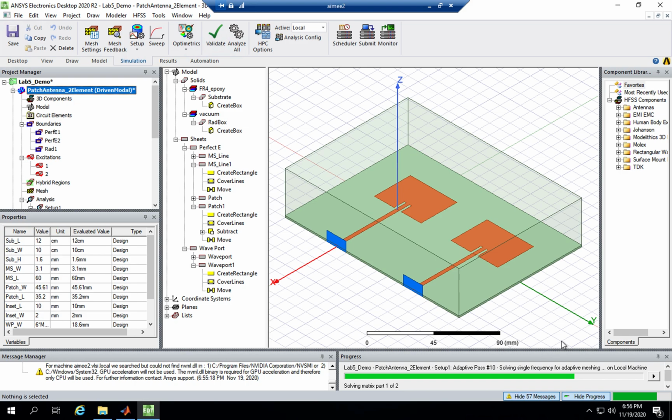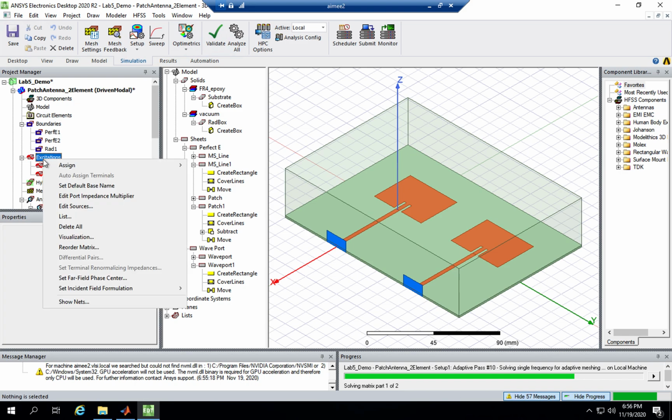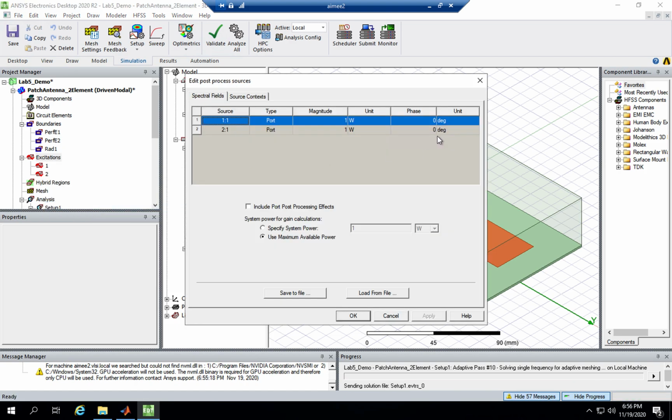Let me go here to show an example. If you need a phase progression, you can set the first element at 0. The second one is going to be 0 plus 1 phase progression. The third one will be 0 plus 2 phase progressions. So if the phase progression is, let's say, 50 degrees, the first one will be 0, the second will be 50, the third will be 100. So that's what the phase progression means, and you'll do that for part 3.3.